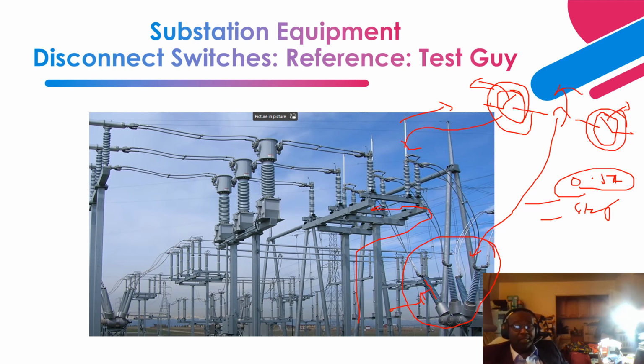Next, it's a tower structure, right? This is what basically supports the transmission lines coming in and going out. Okay, and this one is an example of a current transformer, and I told you how to identify it: it's connected in series. As you can see, two conductors, basically designed so that they split the current to avoid heating. Make sure the sizing of the conductors is correct.